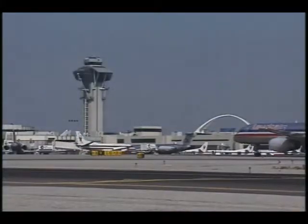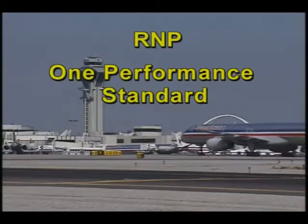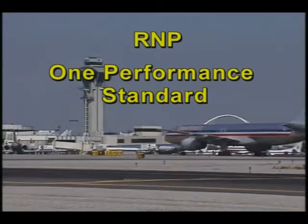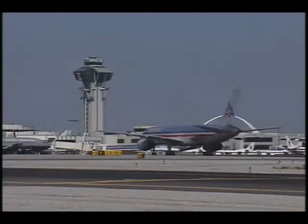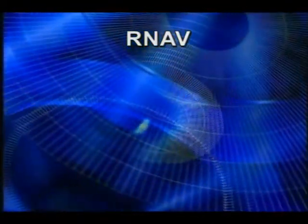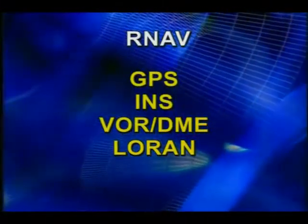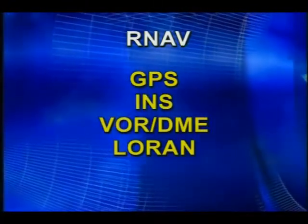The theory behind RNP is to establish one performance standard that applies to aircraft, airspace, pilots, air traffic controllers, and international aviation authorities. This single performance standard is enabling the widespread use of area navigation, or RNAV. The term RNAV no longer refers solely to the VOR station mover of the past, but rather encompasses several different types of navigation equipment. The heading RNAV applies to GPS, INS, VOR DME, and LORAN-based navigation systems.